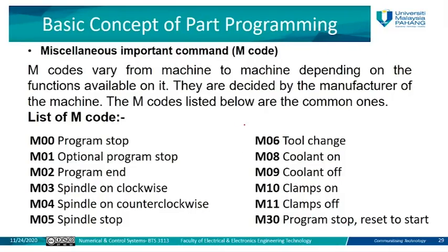So all these commonly used M codes will be listed in the block based on the previous order or sequence that we mentioned. It depends on what function you want to do. For example, I want to use just one M, so you just use it to stop the program. I want to use one M to return or to reset, so I use one. I use one M just for coolant on. Without off, it's okay, just use it for coolant on. So it depends on what is required to produce the product.